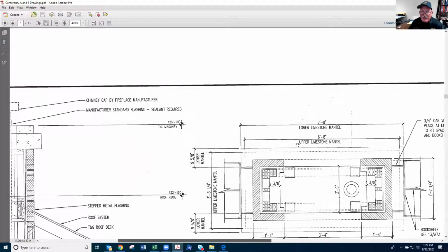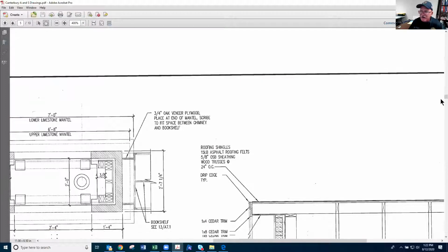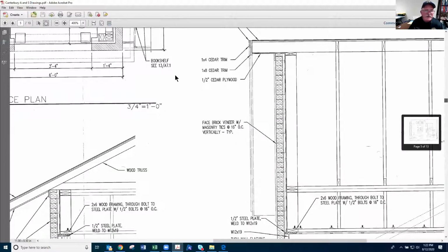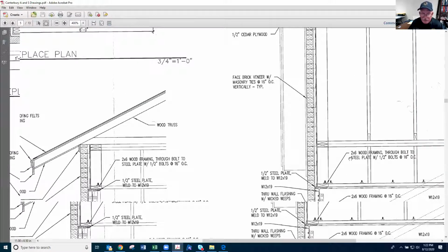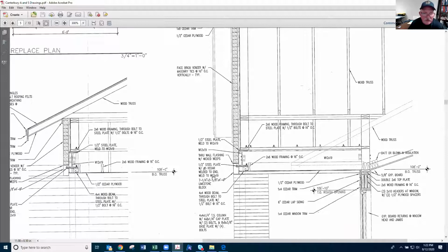the different maintenance type thing, and the mantles and that kind of stuff, because these chimneys also have to have some kind of fire resistance and rating, so it might make a difference to us. Say the brick veneer, the bookshelves, all these have, and it tells us what's needed here. Again, on the bottom of these pages, you'll find the details. You'll find schedules and that sort of thing. Be sure to look at these details here, what's supposed to be there, and what's required insofar in the fire plans and that sort of thing.